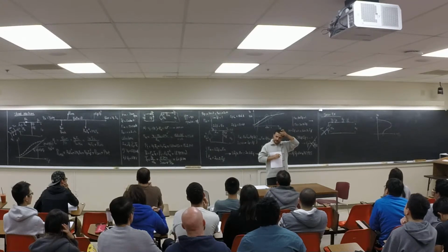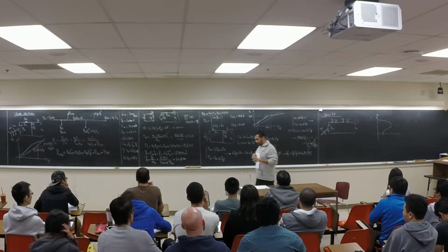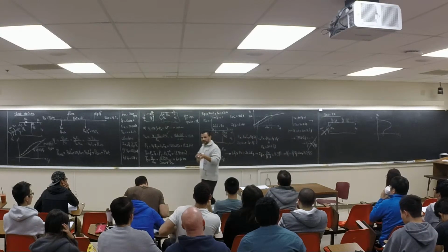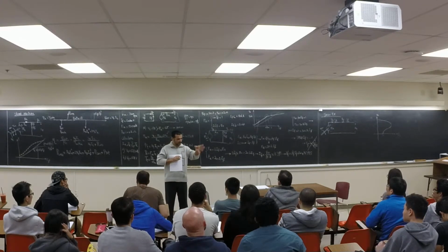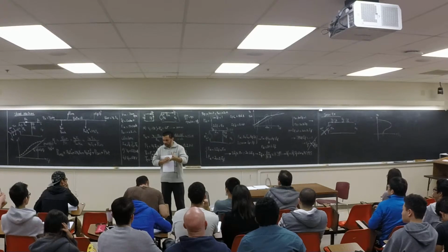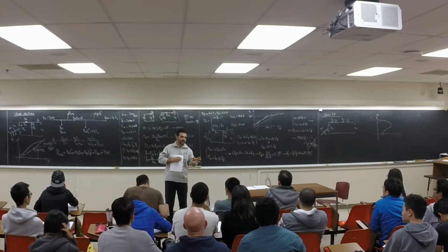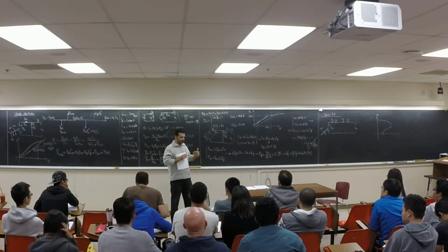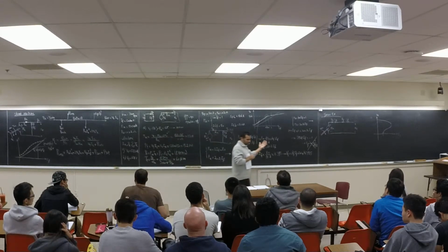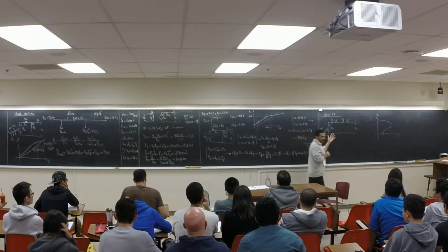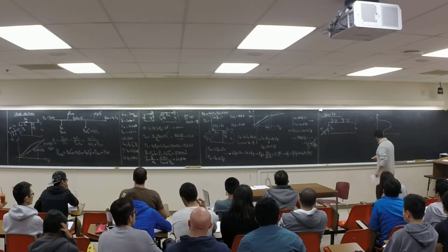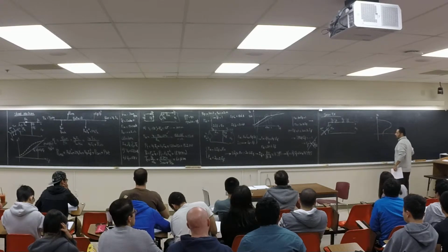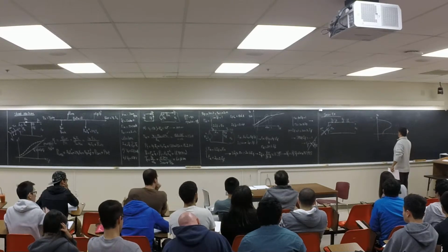But here, I'm just giving you all these things. If, for example, you read in the book, it says we have this drill, which is series excited. So at least you can look at it and ask, what does it mean when this is series excited? So the circuit is this, the torque equation is this. Oh, I understand why they're using series excitation. My point here is that this is a circuit we're introducing, but each of them has its own application, where to be used. Now, let's go through the series excitation.